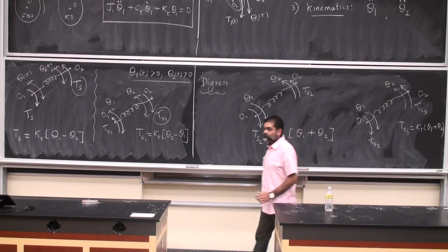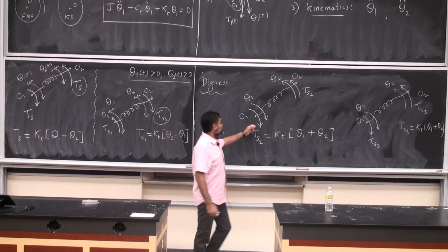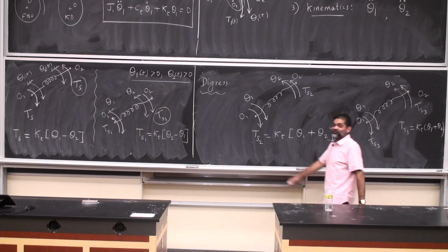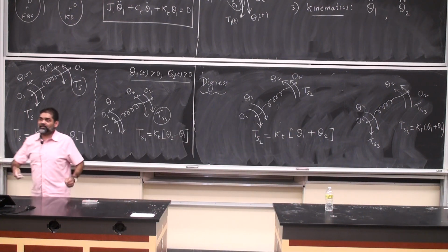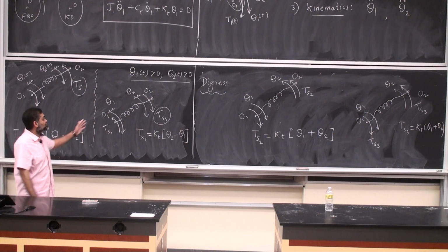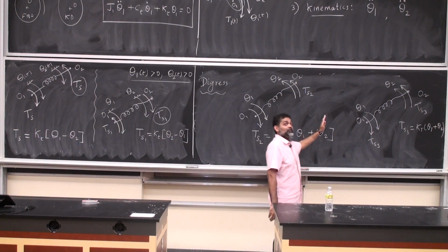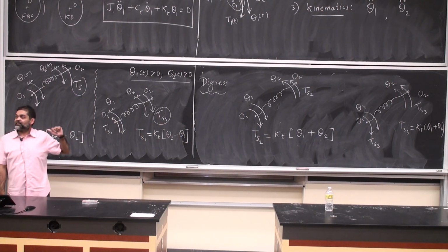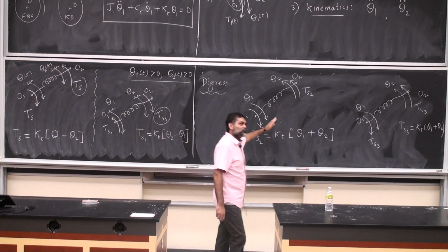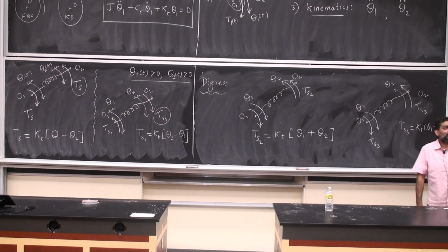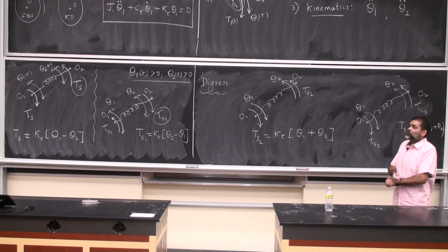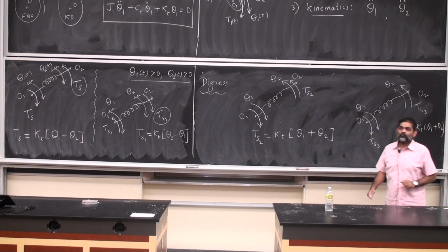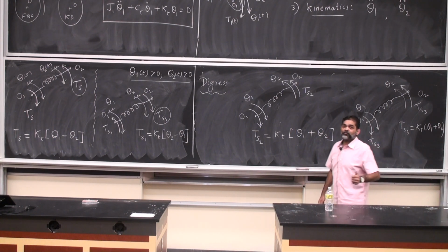And so I see that, okay, this is the same thing. And you see this is quite beautiful, right? Because even the signs of the torques are the same. The directions of the torques are the same. As opposed to the situation here. Okay, here they were at different directions, but then they were also different by a negative sign, so everything worked out here. Here there is not much thought required at all. Everything anyway works out. Does this make sense to everybody? It's very critical that we understand this. If you do this, the dampers just follow suit. You don't need to do any calculations. Just do a theta 1 dot and a theta 2 dot. That's it. Same idea. Last chance for questions.